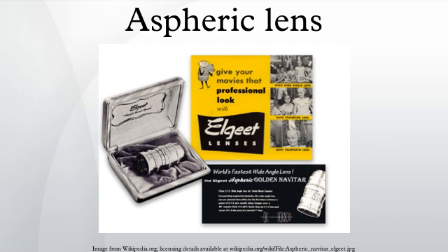The non-spherical curvature of an aspheric lens can also be created by blending from a spherical into an aspherical curvature by grinding the curvatures off-axis. Dual rotating axis grinding can be used for high-index glass that isn't easily spin-molded, as the CR39 resin lenses. Techniques such as laser ablation can also be used to modify the curvature of a lens, but the polish quality of the resulting surfaces is not as good as those achieved with lapidary techniques.